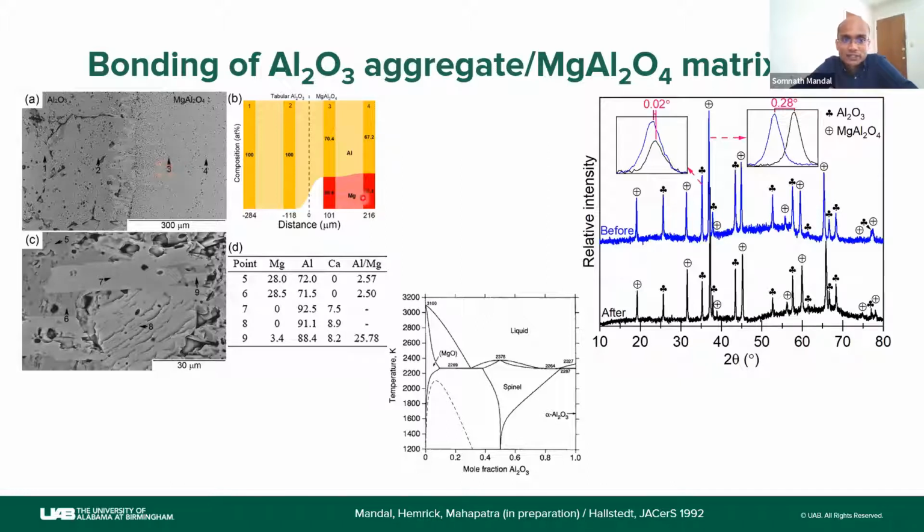is that there is a lot of solid solution formation, and we all know this is alumina, this is spinel, there is this wide solid solution region. That's what you are seeing here. At high temperature in the interfacial region, there is this solid solution formation, and during the cooling of the sample, it precipitates this corundum phase. All of these bright ones, 7, 8, are corundum phase.